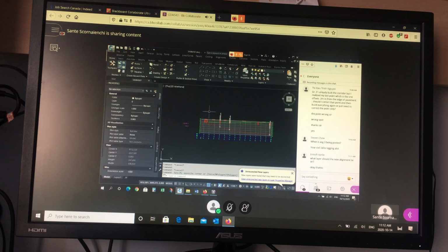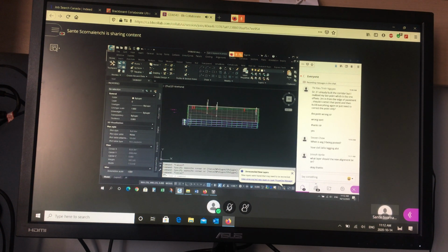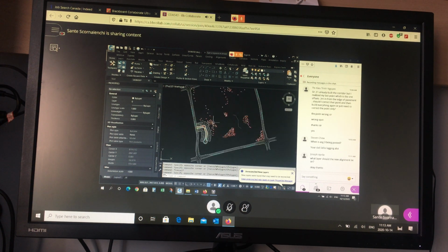Well, I'm going to treat 0 at this end, right? I've got 0 here. Positive chainage is increasing from left to right. So I'm going to lay out this profile on the top, up here instead of down here. So anything I draw for a widening on the left side is going to be above. Anything I draw on the right side is going to be below. So it depends what your road's doing, right? Mine is turning to the right, so the left side of the road is my widening. If yours is turning to the left, the right side of the road is widening. Okay, so the definition of left and right depends on the direction of increasing chainage.